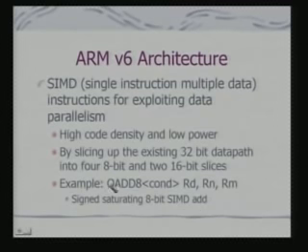So when I am talking about QADD8, it means I am not talking about a 32-bit addition, I am talking about 4 8-bit additions, and that is why this is an example of a SIMD instruction, okay. So corresponding bytes get added and I use saturation arithmetic.